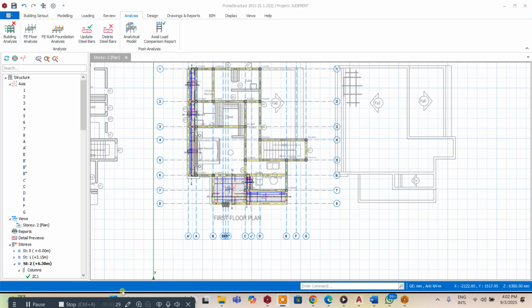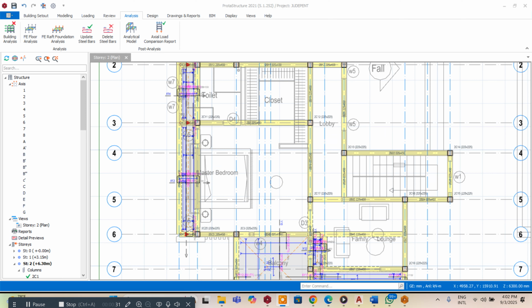Now, by practice, I've observed that any span that is up to 5 meters, or let's say 4.5 or 4.8 thereabouts, if you don't introduce an intermediate beam between a short span, at the end of the execution of the project you discover that at that particular place your roof may be sagging, because the type of timber we use this time around does not have the required strength to carry the load from the roof.